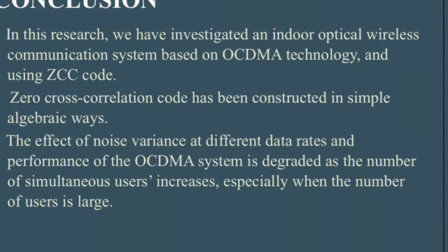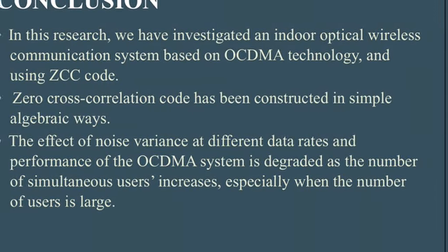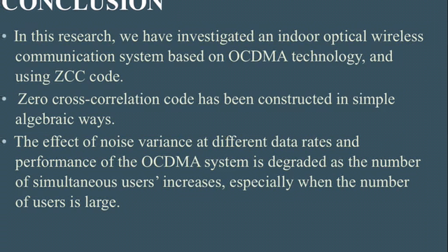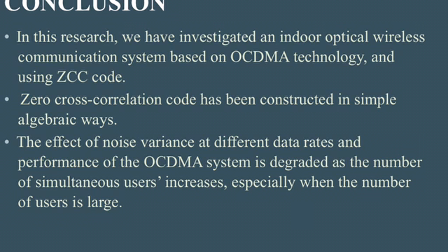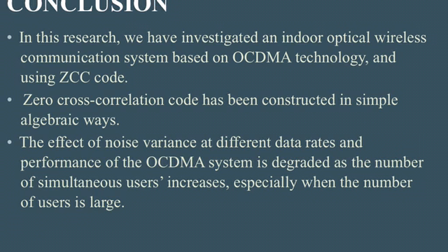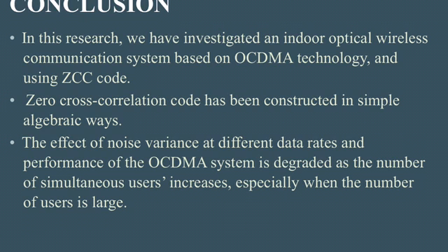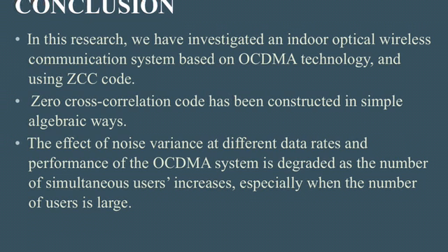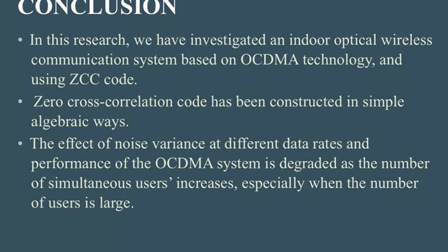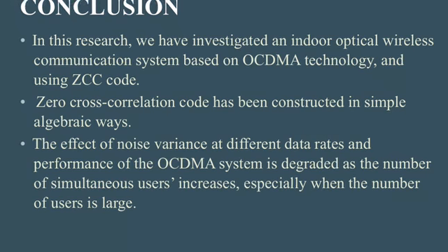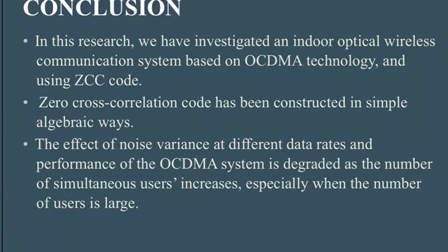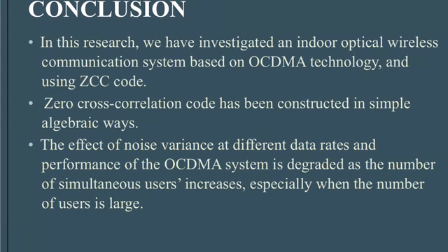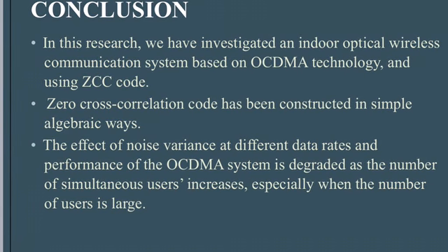For the conclusion of this research, we have investigated an indoor optical wireless communication system based on OCDMA technology and using ZCC code. Zero cross correlation code has been constructed in a simple algebraic way, and the effect of noise varies at different data rates, and performance of OCDMA system is degraded as the number of simultaneous users increases, especially when the number of users is large.